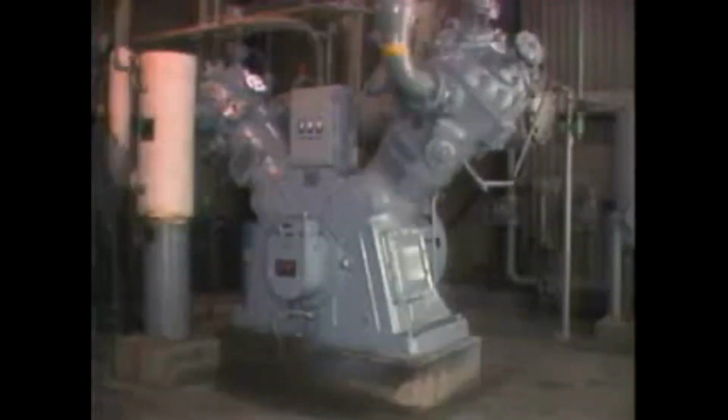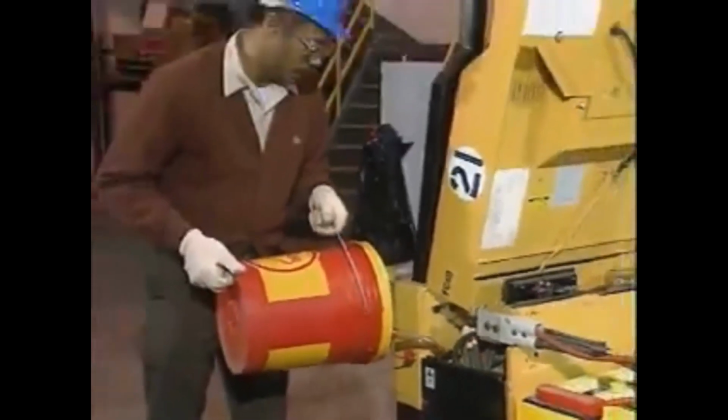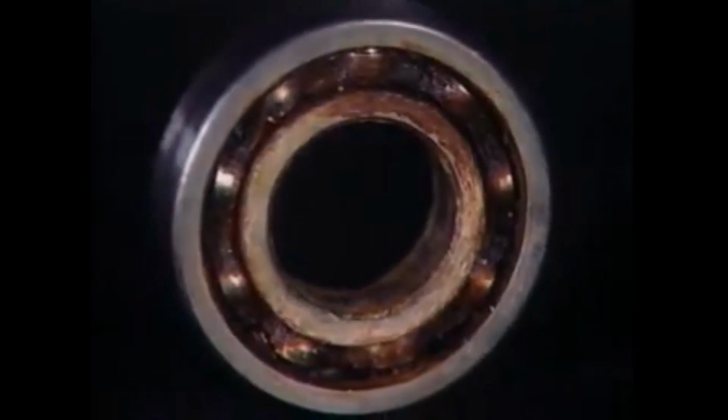Resistance to oxidation is another significant property of lubricants. It refers to a lubricant's resistance to reacting chemically with oxygen when exposed to heat and air. You see, many industrial lubricants are made from hydrocarbons. When the hydrocarbons are exposed to heat and air, the chemical reaction called oxidation occurs. Oxidation causes chemical changes that destroy a lubricant's effectiveness and lead to the creation of deposits such as sludge and varnish.